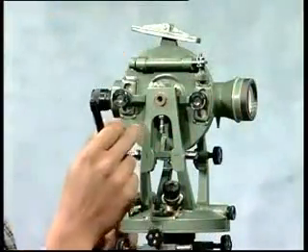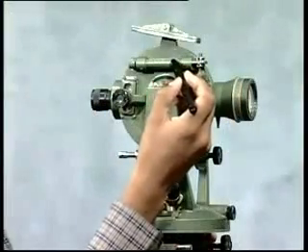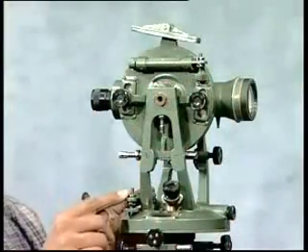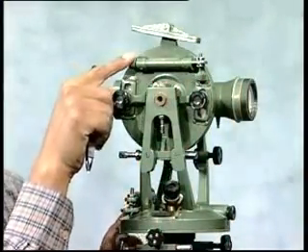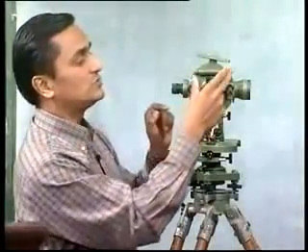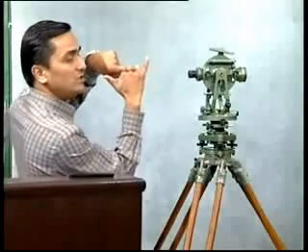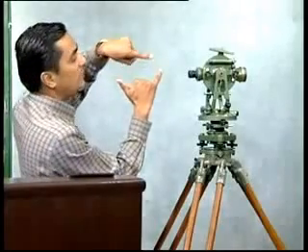In order to ensure this, we have an additional bubble tube here. It's a similar bubble tube to this, but it is more sensitive. We'll talk about the sensitivity of the bubble tube later. But using this bubble tube, we can make our index horizontal. So basically, the bubble tube is kept on the index. So by making this bubble tube horizontal, this index can be made horizontal. So we can draw it here in the diagram also.